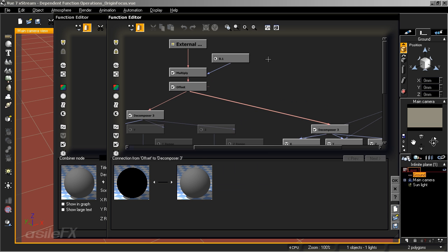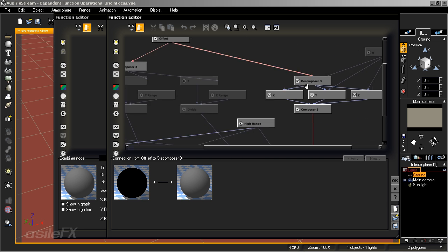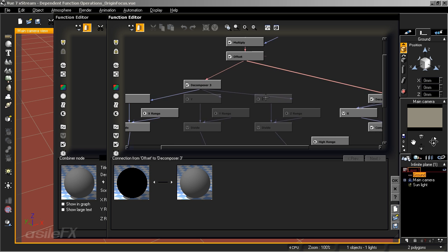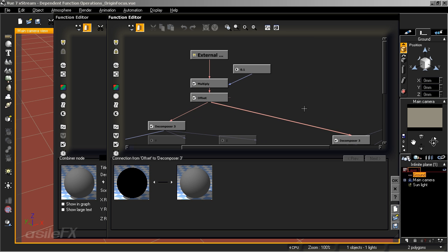And what we need to take a look at is what is causing this issue. Basically it's because we're grabbing our vector for our vector output from our internal unit correction. Well, that's primarily for manipulating numbers, which is great for modifying the blenders like we did before. But right now, we need to focus on the vector, and we're going to be using this as an offset to control different nodes and offsetting them in a couple of different ways.